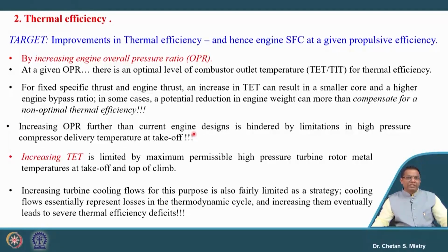So, just realize the case, we cannot increase the overall pressure ratio to a very high number, because when we are moving towards a very high pressure ratio, if at the same time my turbine entry temperature is lower, then it is a violation of our thermodynamics. We have discussed these aspects when I was discussing our turbojet engine class. So, just revisit that class.